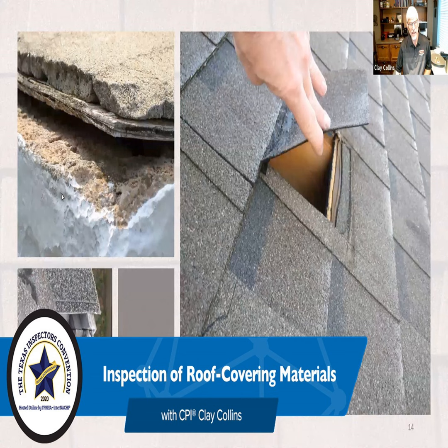They just coated it with some sort of roof sealant, and I think that's about the worst way you can do it, because you can see from the size of that repair, they didn't know where it was leaking. So they just kept on applying sealant until it took care of it. You see it goes all the way up the valley flashing. That's probably the worst thing that could be done, and that was probably done by the homeowner.